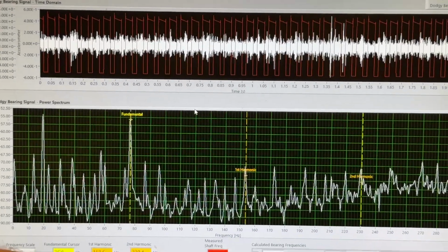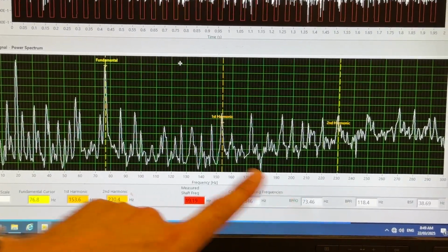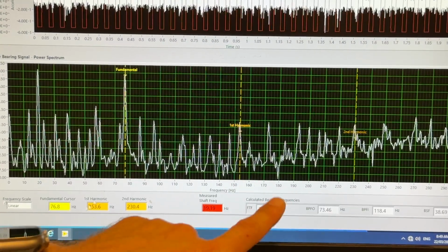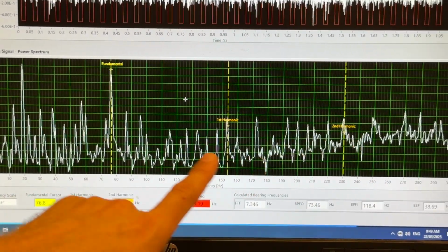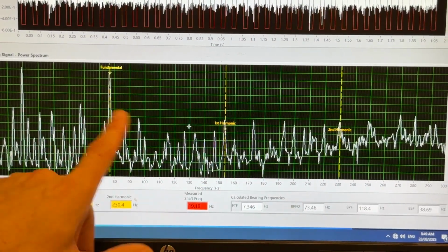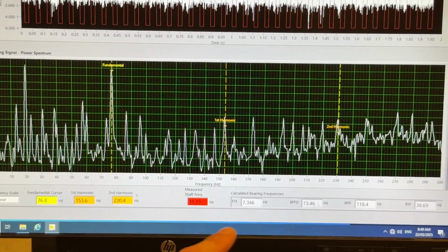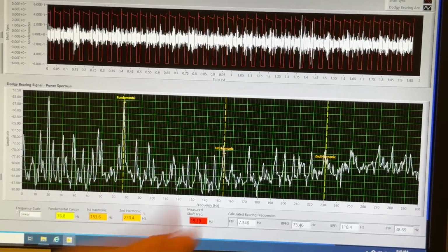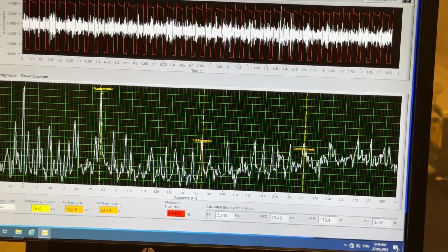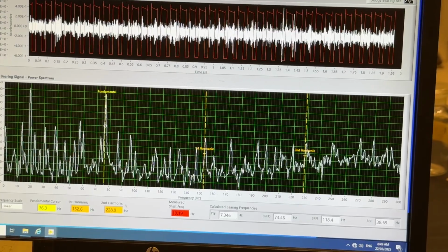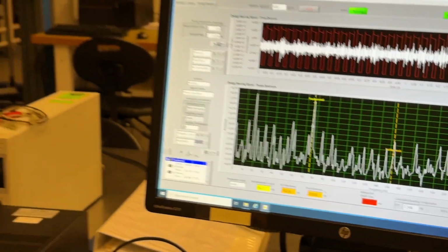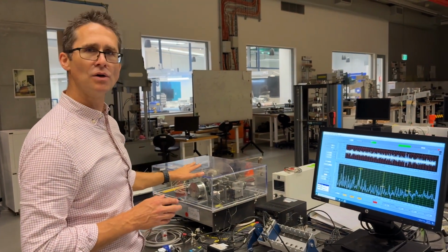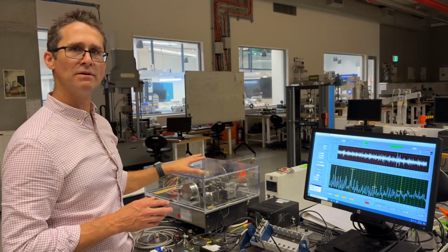to determine these frequencies. And we can use these frequencies to help us interpret that this peak, which is at approximately 76 hertz, and its harmonic multiples, first and second harmonics at 2 times and 3 times, are clearly related to the bearing ball pass frequency on the outer race, which is around about 74 hertz. And that's how we use this kind of equipment to help demonstrate how we can use vibration analysis to diagnose challenges, problems, faults with bearings and rotating equipment.